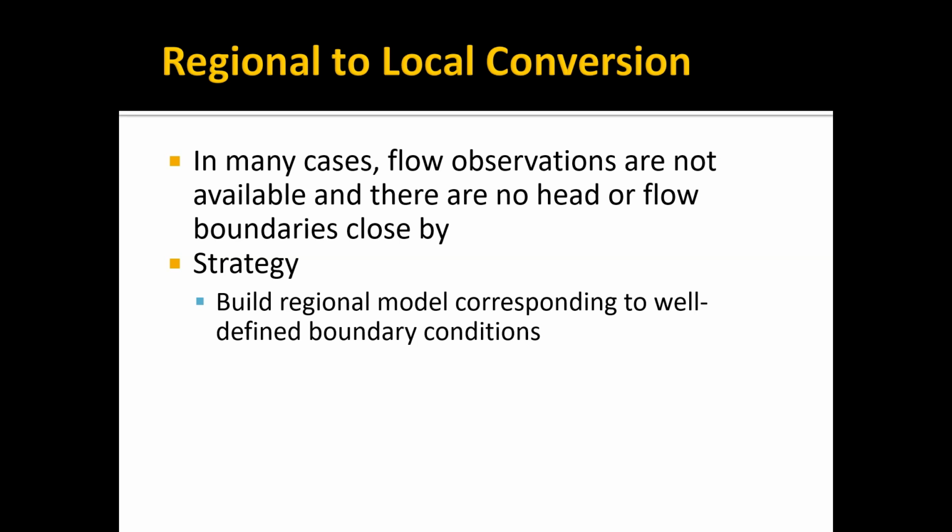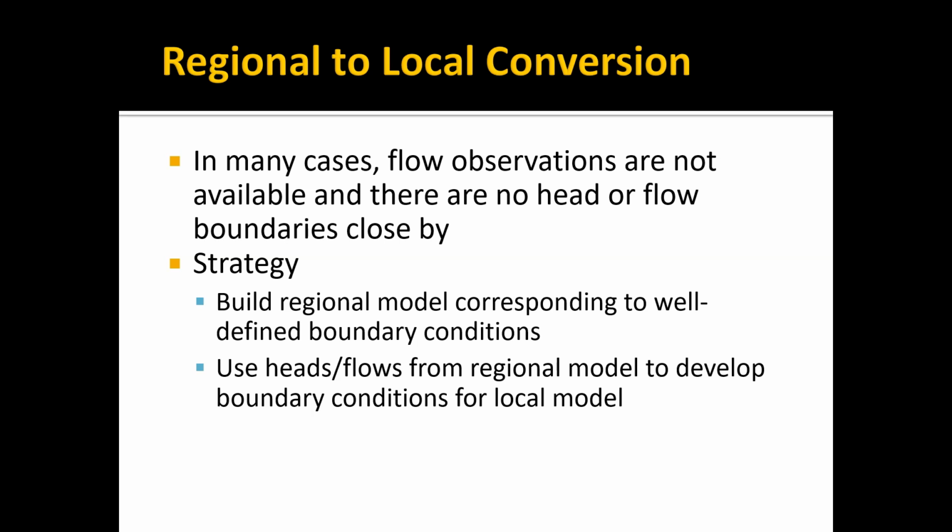and then maybe do a parallel flow boundary on the top and bottom. One of the challenges of that is now you have to incorporate probably a lot more wells in your system, and more hydrogeology you have to interpret, but even if it's an approximate regional model, it's better than nothing. And then if you calibrate that, by extending the model to where you have good, well-defined boundary conditions like I just described, then you have more confidence in that regional model.